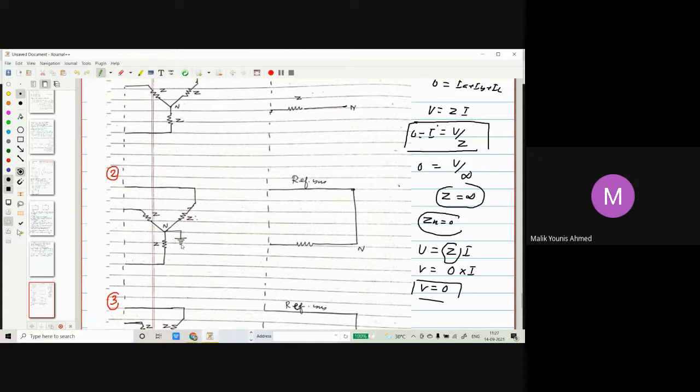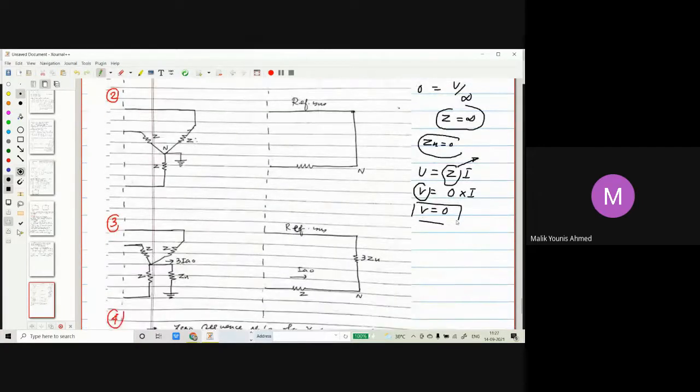A wire is there and that's grounded. So when the value of this impedance is 0, that means your voltage will become 0. When your voltage becomes 0, that in electrical engineering is represented by a short circuit. So between one of the phases of the star connected, because we are drawing the sequence networks on per phase basis, this is your Z here, and between the reference, that's the ground potential, and the neutral point, there will be a solid short circuit, connected by a wire.